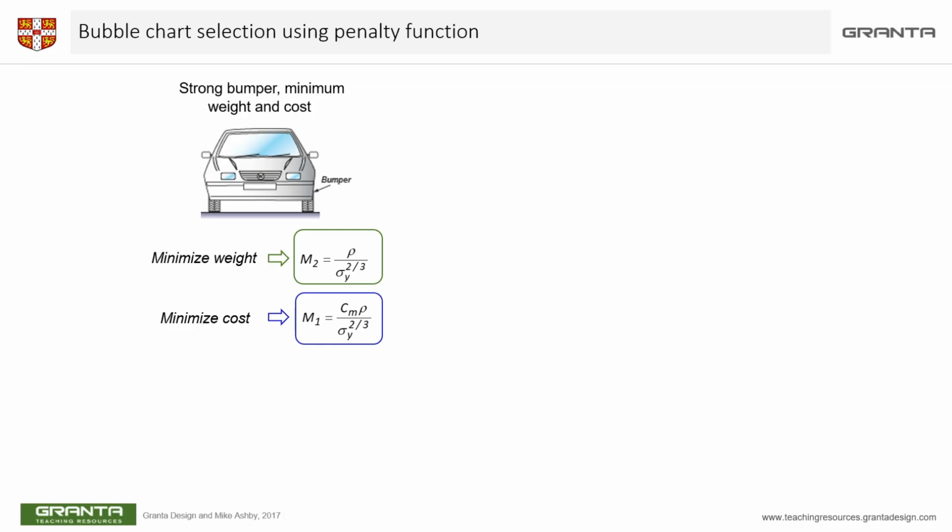Maybe, first of all, you'll consider what your primary objective is. Based on that primary objective, you will carry out a multi-constraint optimization. Then, from the best 10 or 20 materials based on the primary objective, you'll move to a multi-objective phase where you can compare those remaining options, and then focus maybe on just one constraint, right?